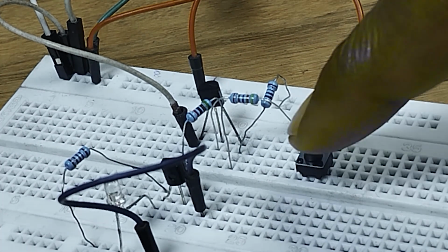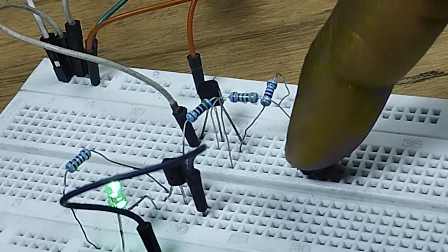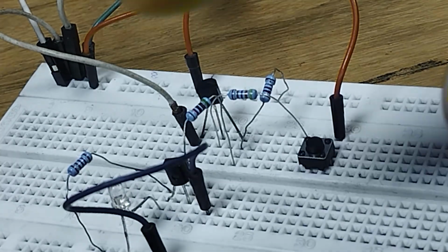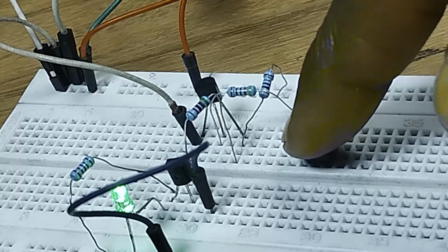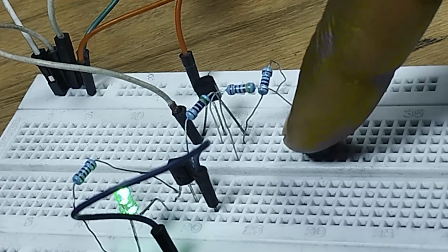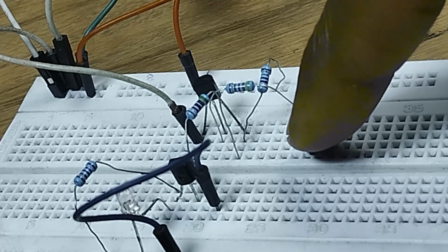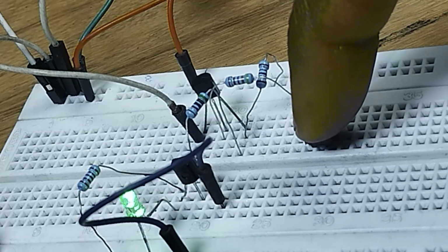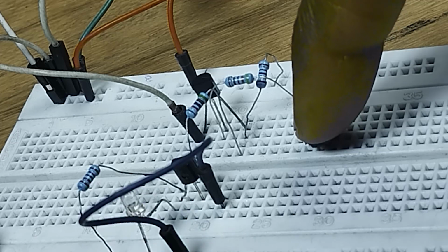And like we said, when you give a high to the base, the output turns high. When you send the low to the base, the output turns low. So the buffer circuit output level follows the input level. Okay, so this basically, like was said, is used to isolate logic gates, and they can also be used to switch loads on or off.